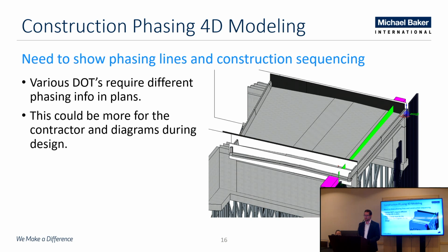Say it's a slide bridge, right? You've got the initial location, you model that, now you've got your final location. All you have to do is adjust your horizontal alignment, or horizontal offset, sorry, in that new model, and now it's in its new location. So you've got, say, 4 separate models of the same bridge, but in different locations, or maybe certain aspects of that are cut off due to construction phasing. And then I'll show you how those are combined together here at the end and shown in a way that the contractor can identify and understand that phasing.